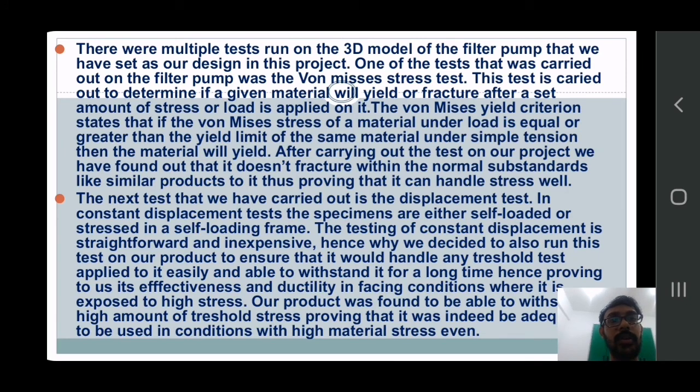There are multiple tests run on the 3D model of the filter pump that we have set as our design in this project. One of the tests carried out on the filter pump was the von Mises stress test. This test is carried out to determine if a given material will yield or fracture after a set amount of stress or load is applied on it. The von Mises yield criterion states that if the von Mises stress of a material under load is equal to or greater than the yield limit of the same material under simple tension, then the material will yield. After carrying out the test on our subject, we found that it doesn't fracture within the normal sub-standards, like similar products, thus proving that it can handle stress well.